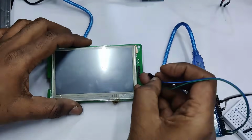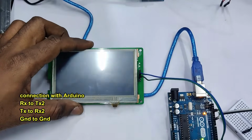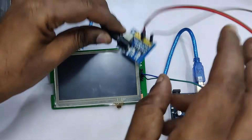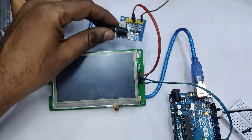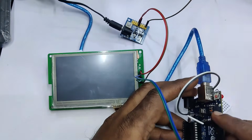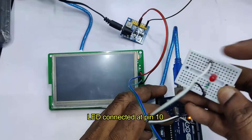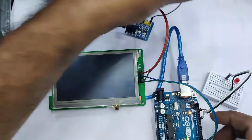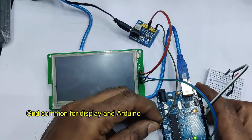The connection is same, that is TX to RX, RX to TX, and ground is common. RX is connected to TX2 of display, TX is connected to RX2 of display, and ground to be common. That is very important. Now let us provide the power supply 5 volt and ground to the display, and then let us connect an LED at digital pin 10, and the other end of LED is connected through resistor to ground. So ground of Arduino and ground of display both should be made common. This is very important, otherwise the data will not be transmitted. Ground is made common.